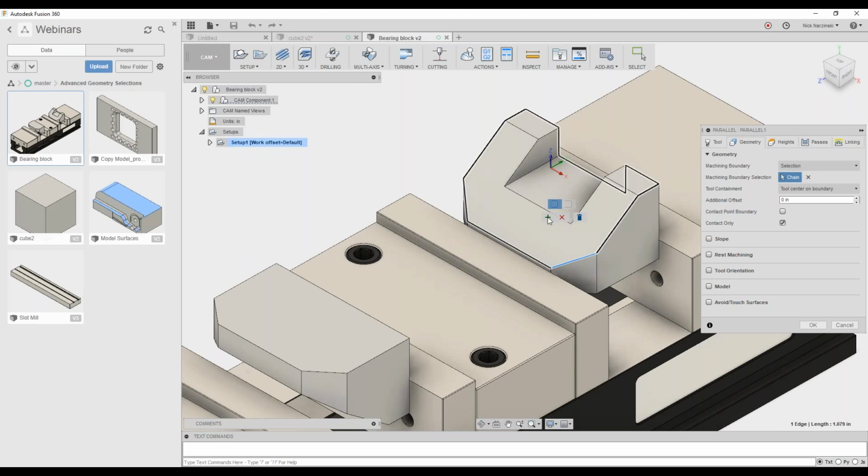If you need to edit that, I'm going to pick that profile again. That puts it into edit mode. So now you can see these selection tools. The way this works is you just re-guide the toolpath. So I selected that edge first, it's blue. It looks good all the way around up until right here. It goes where I don't want it to.